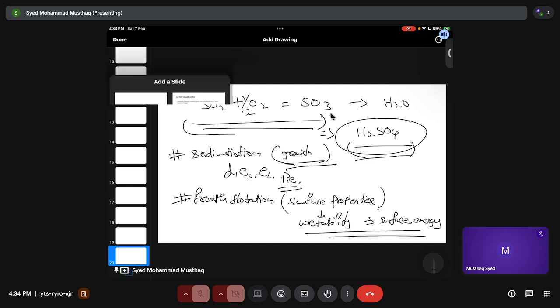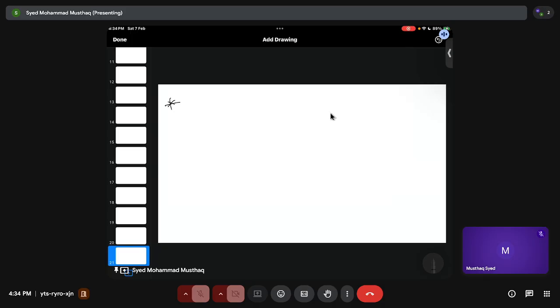Now again, when we are talking about magnetic separation, we defined our materials. We have different materials, right? You have paramagnetic materials and diamagnetic materials. So we have different types of materials. Paramagnetic materials have a susceptibility greater than 0 but small. For diamagnetic materials it is less than 0, which is negative. For ferromagnetic materials, susceptibility is greater than 1, right?